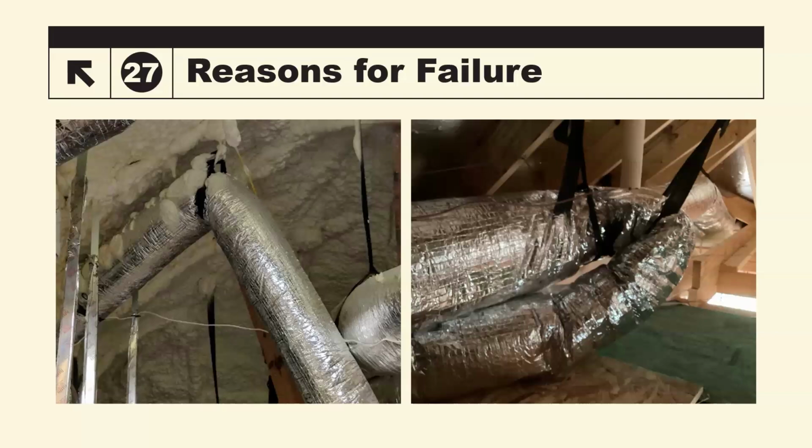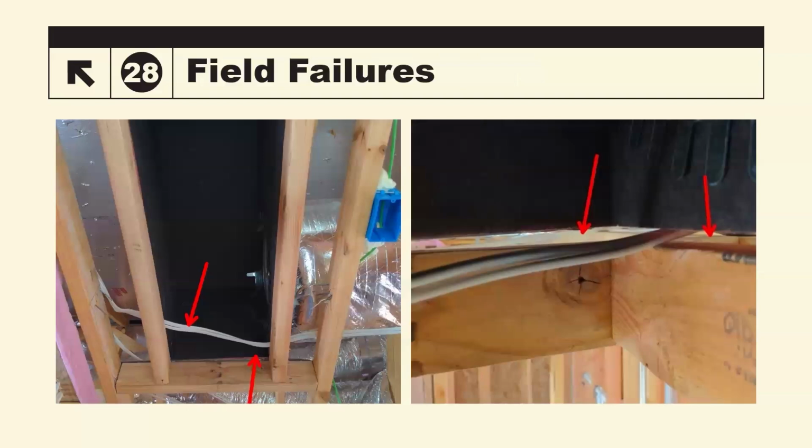So we've looked at these photos in previous webinars. We've talked about proper duct installation, but it is more than just the effect on airflow and crushing of the ductwork. It can actually turn into duct testing issues, because you have compromised airflow within the system. And you've probably seen this one before too, electrical wiring run through and under or around or directly into a return plenum. While this may or may not be something against code, this really shouldn't be happening. It should be planned out correctly. But at the very least, this should not just have a heavy ton of mastic slapped on here to try to seal it up.